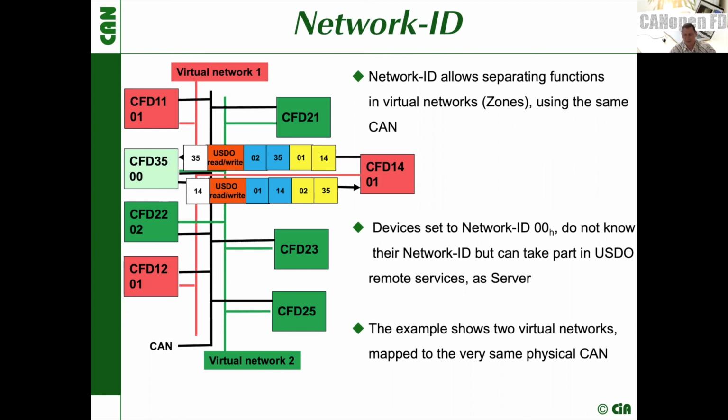You have to be a little careful that you don't mix it up with other devices claiming network 1, 2, 3. So node IDs still have to be unique in your network. But you see, this network ID opens the door to manage more complex embedded network challenges in the future, or that you may already have in your applications.